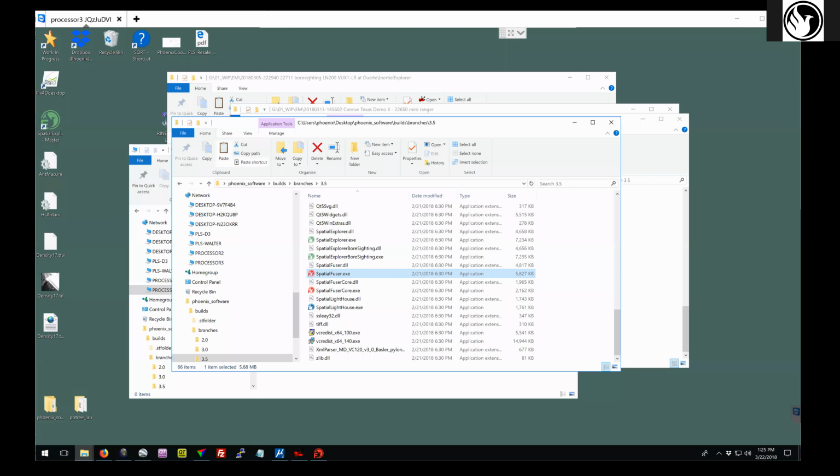LiDARMill processes, so the first step is to upload all your data, which should be right here. Exactly what we do in Inertial Explorer and Spatial Fuser, we want to upload our nav files, our reference file, which is our static station. If we have camera data, this can colorize the points as well.